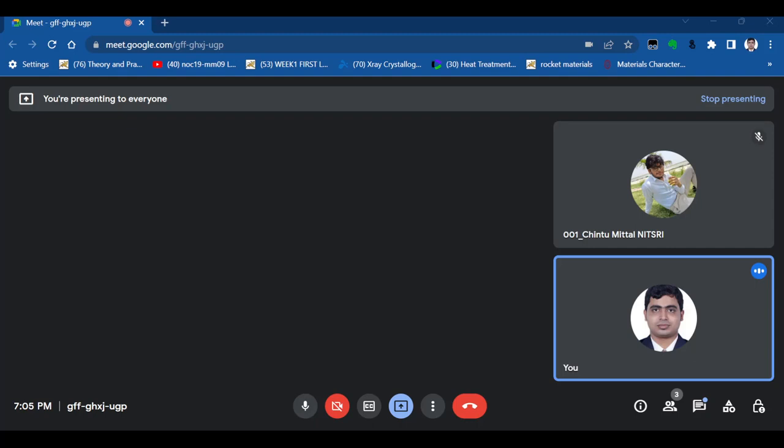Like if it is a surface crack, then this is 1.1. If it is a center crack, then this A is 1. So here you don't have to consider this, just forget it. Here a is the semi crack length, and sigma is the applied stress. So this is the same for both cases. So what should happen to the crack length a? Which material can withstand a larger flaw size, X or Y?